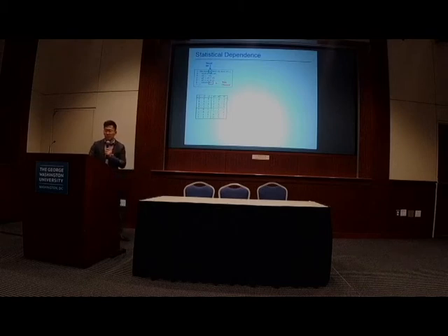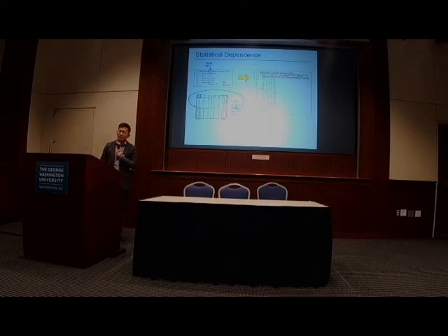So here is the truth table. I have I1, I2, I3 can be from 0, 0, 0 all the way to 1, 1, 1. And this is a secret bit. I don't want you to know whether you're in the first half of the truth table or the second half. But you can observe N1. So if you measure the power, you would see the difference. So that's the leakage.